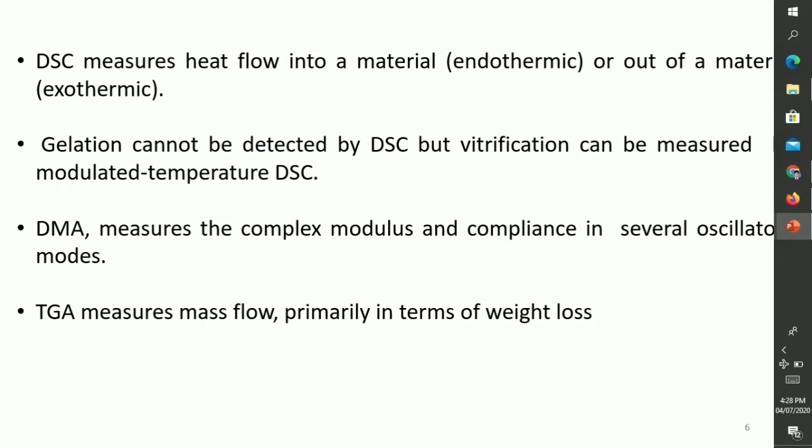Gelation and vitrification can be detected, and the cure reaction can be monitored via glass transition and beyond the gel point in the absence of vitrification via modulus.